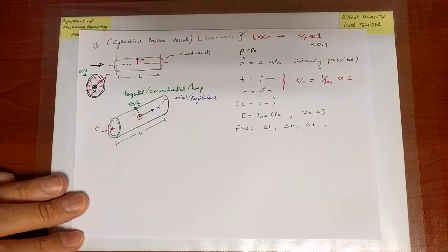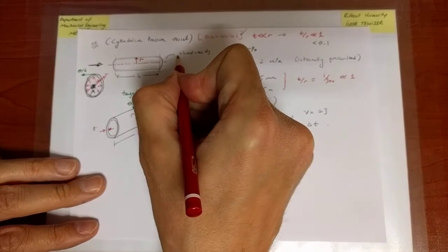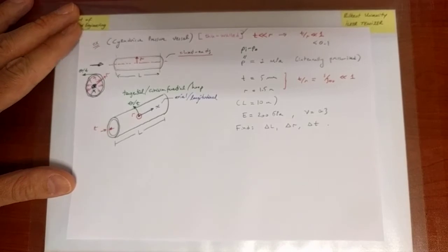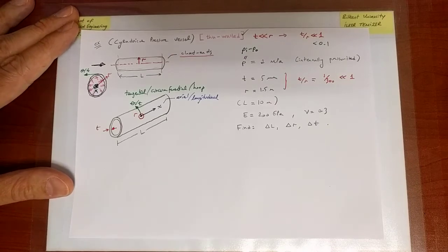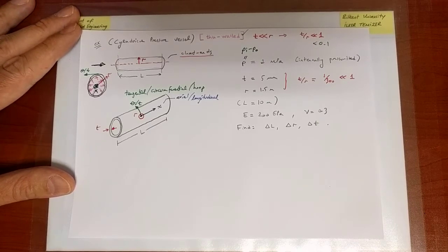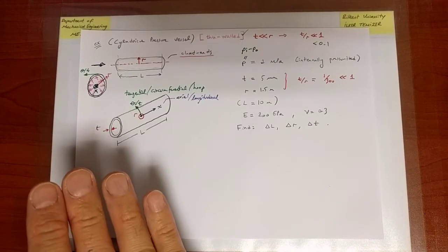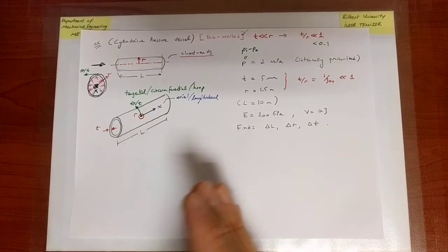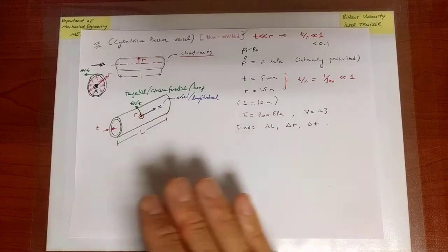We're now going to attack that question based on the important assumption of a thin-walled vessel plus the fact that we just called it closed ends. Right? So let us go ahead and now attack this problem. And the first thing I'm going to try to do is calculate the stresses that are associated with this coordinate system. So first of all, irrespective of the type of coordinate system you use, Hooke's law will always hold. So in other words, there will be normal strains and normal stresses associated with three directions.